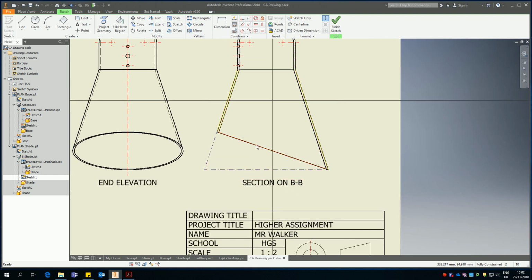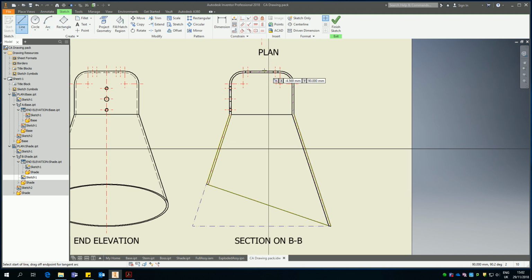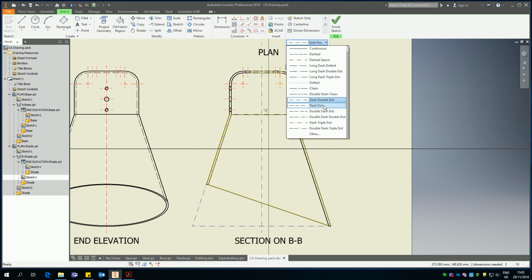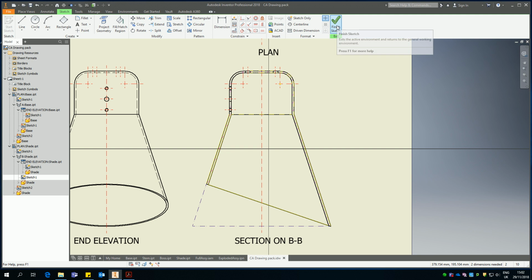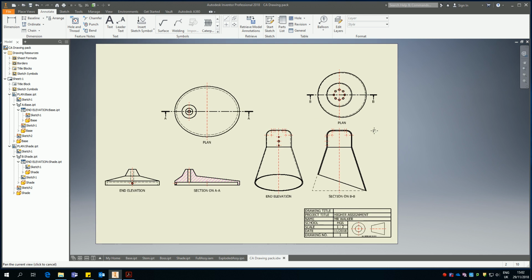Now this will help me later because it means I can put the angle dimension in there as well. I just want to add the line going down from the bottom, so from top to bottom. I'll put a vertical constraint on to position it into the middle. I know it's correct then. I'll just use the red and dash dot. Okay, and that is, alright, that is these fully center-lined.